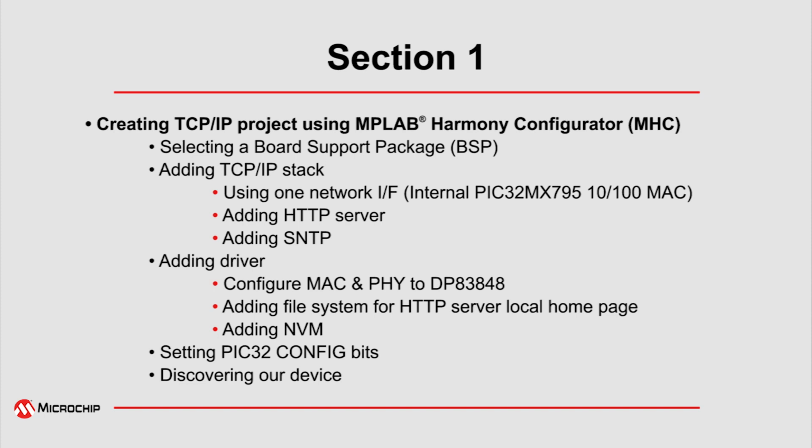We will add Simple Network Time Protocol to allow the SSL library to validate the issue date and expiration date of the certificate provided during the SSL connection. We'll be adding drivers to configure the MAC and the PHY attached to the PIC32MX. We'll be adding the file system for the HTTP server to retrieve the local web page. And we'll be adding NVM, or non-volatile memory, to store that local web page onto the onboard flash of the